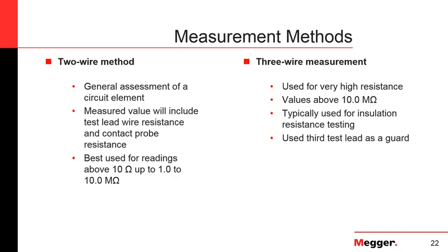That's a good question. Like I said, if we do the winding resistance on the transformer, and we know that we do that with DC current, that will magnetize the core of the transformer. And if we don't demagnetize the transformer, then when we put it back in service, because of that residual magnetism, the first inrush current when we energize the transformer will be huge, and that of course will cause damage to the core of the transformer.